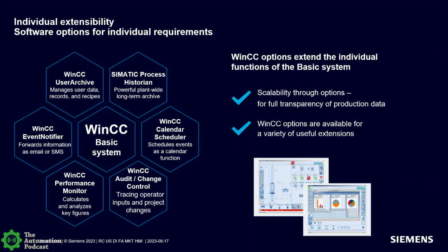Performance Monitor, that's our KPI analysis tool. So it's an open tool that plugs into WinCC, and you can sit there and start defining and writing different scripts, or not scripts, but different formulas that you need to create KPIs. If you just want something as simple as uptime versus downtime as a percentage, just pull the tags that are giving that information, build a little math formula and start displaying it as a number on the screen or a graph on the screen. So you can start doing your KPIs and see what's really going on.